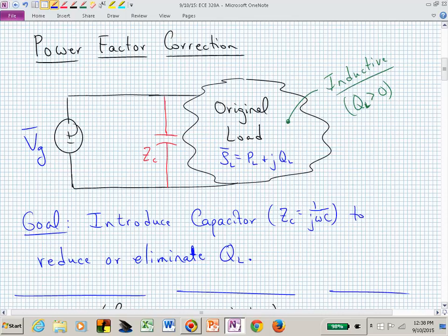Siri may be even starting to do that in a little bit. But now if I say power factor, you're seeing an angle. If I say you have a power factor of 1, what is that angle? 0. You have all real power. If I say you have a power factor of 0.7 lagging, what are you seeing?